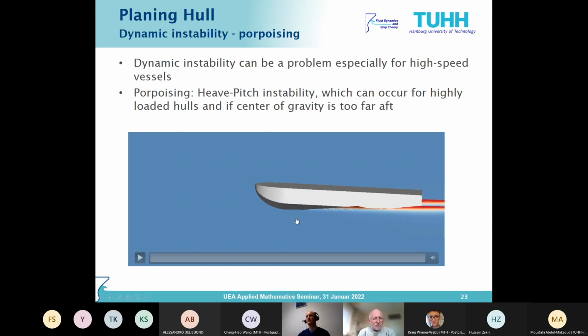Basically it's the same. The boundary values of the hull are always the hull velocity. There's the rigid body, and then there are the cuts, the earth-fixed cuts. Every time step we look at where the cut of the 3D body with the section is. We can calculate the velocity of the hull surface in this two-dimensional frame, and then apply the boundary condition like before.